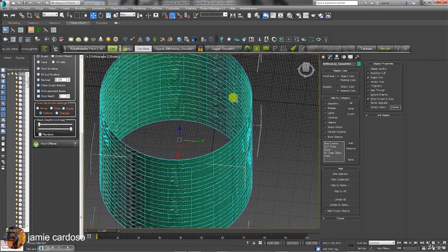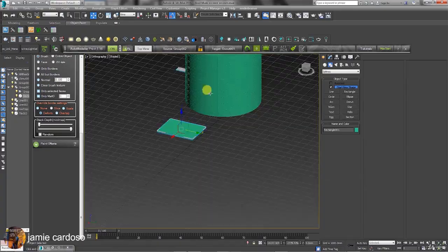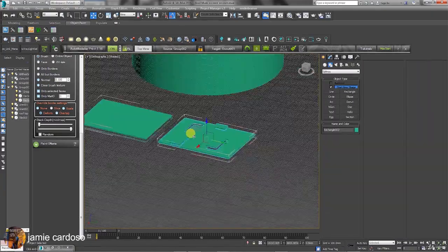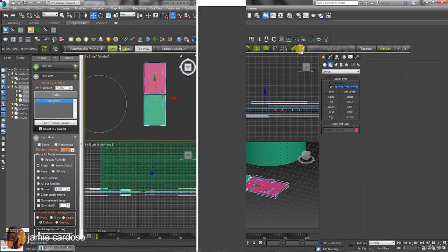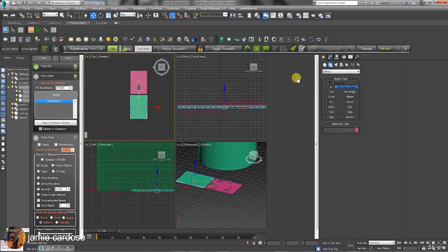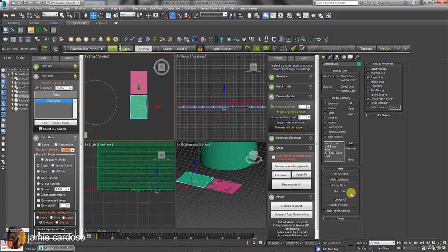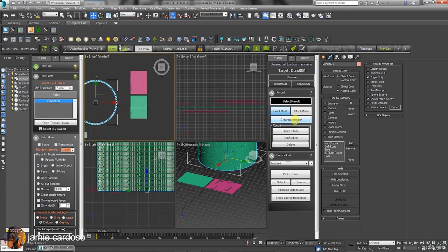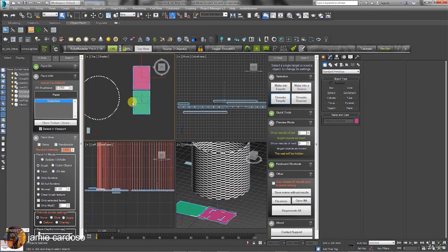To randomize the tiles, we are going to create a new set of tiles and change them slightly. Open the Properties dialog, choose to Unmake and hide, and select the cylinder. Click to clear paint mask. Select both tile objects in the scene. Make them into a source.